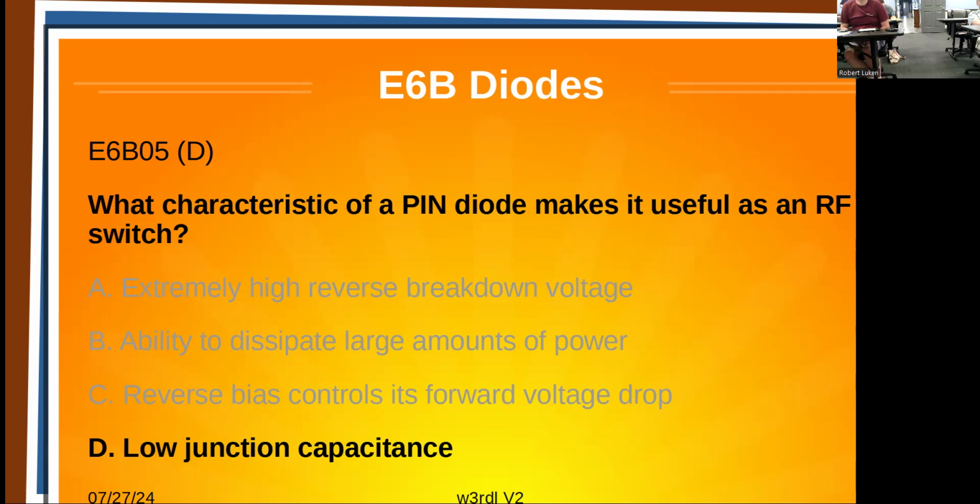But it's normally used at high frequencies as a switch to select bandpass filters. So you can have a bunch of filters separate with PIN diodes and bias those remotely and select whichever bandpass filter you want. That's how most of the modern radios are done, as opposed to using small high frequency relays.